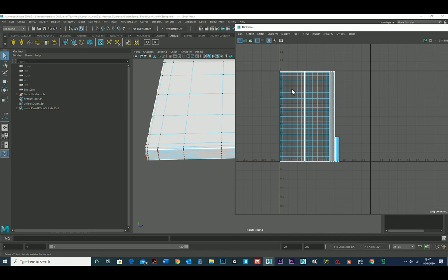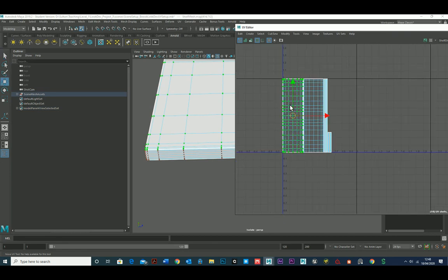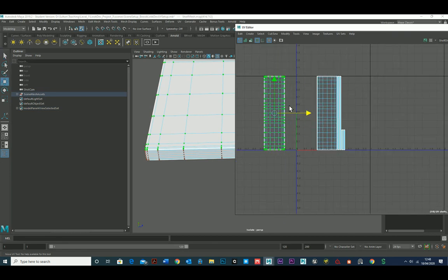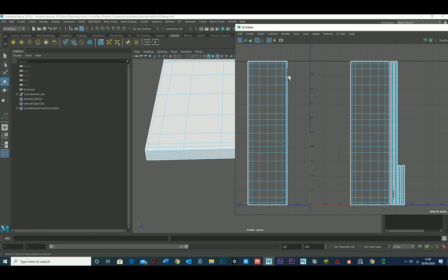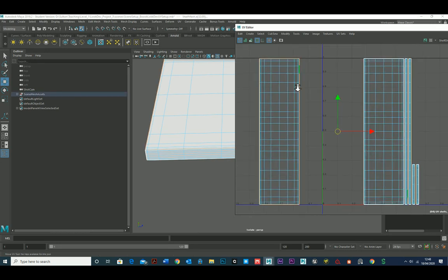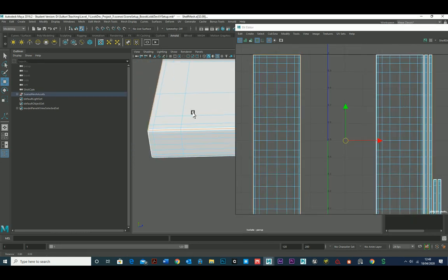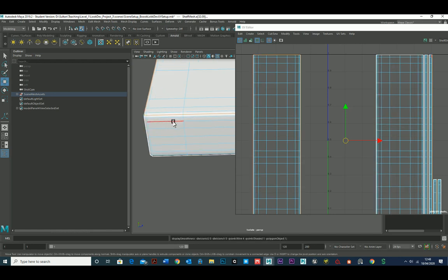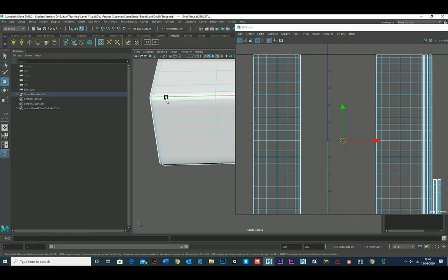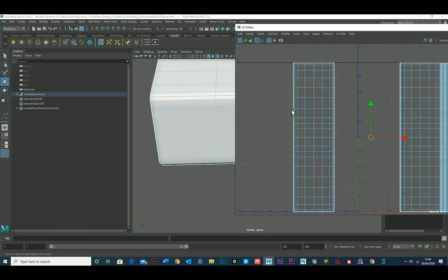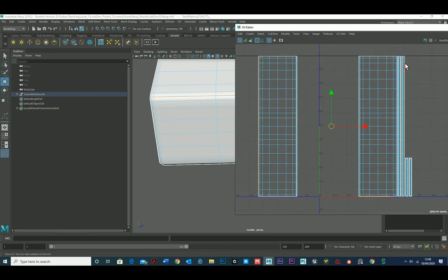So in this case, if I double click on this top plate, I'm just going to move it aside, and holding onto the right mouse button, I can go to edge, and if you select the border edge from here, let me just, it's this one, I think. Let me just go, it's that one. It's going to pick that border edge like so, and it's going to also highlight the neighbor.